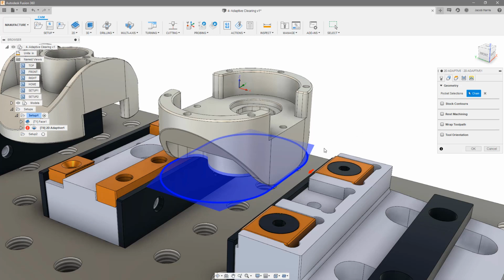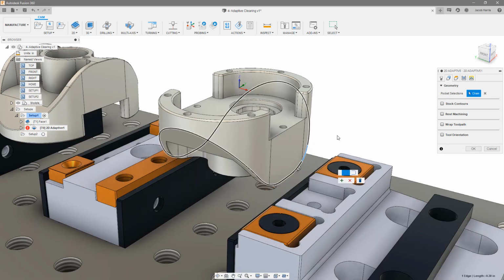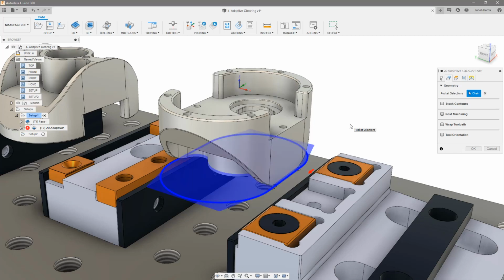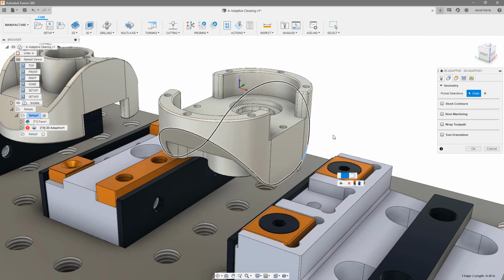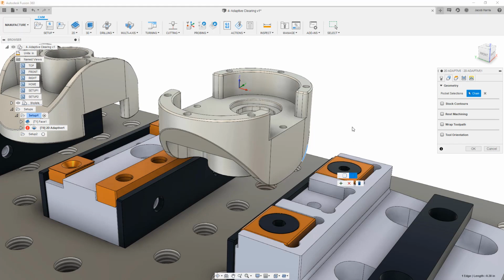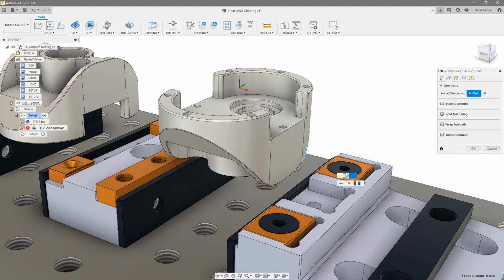This opens the Contour Selection Manager where I can adjust my contour selection by continuing to select contours on my model. Selections highlighted in blue represent contours I have selected, and selections highlighted in black are Fusion's attempt at closing the profile. I can select a closed contour and Fusion will automatically attempt to close my contour selection, or I can select an open contour, which allows me to select individual contours to form a partial chain or individual open contour. One trick is to hold the Alt key to force Fusion to just select the partial contour. Note that it is possible to automatically detect open contour selections.